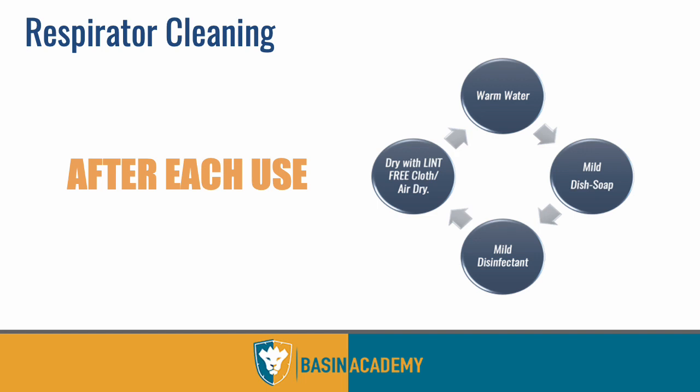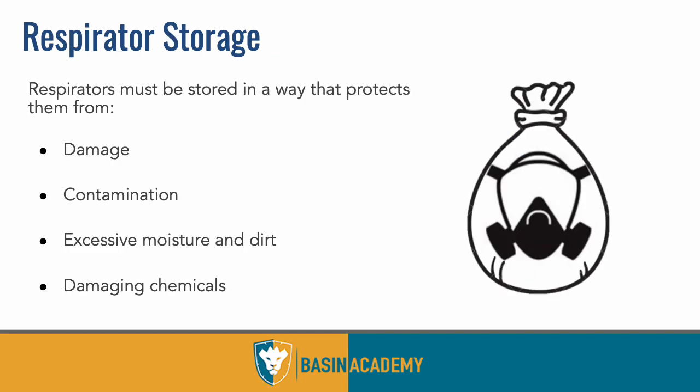And then dry. If we're not going to air dry it, then dry it with a lint-free chamois, something that doesn't have lint on it. It has to be a lint-free chamois because there are different chamois out there. That lint will get in there, get wet, get bacteria on it. Bacteria will grow, make a colony, you'll breathe it in, and the respirator will make you sick. Sorry for doubling that up, but it's true. So we want to make sure we keep it dry and free of any contaminant, including lint.